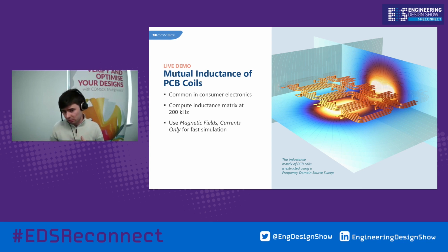So these PCB coils will look as you can see on the slide, and designs like this are common in a very wide range of consumer electronics. So we will go around and excite these coils at 200 kilohertz, which is just a test frequency I've chosen off the top of my head, and work out the inductance matrices between the different coils.